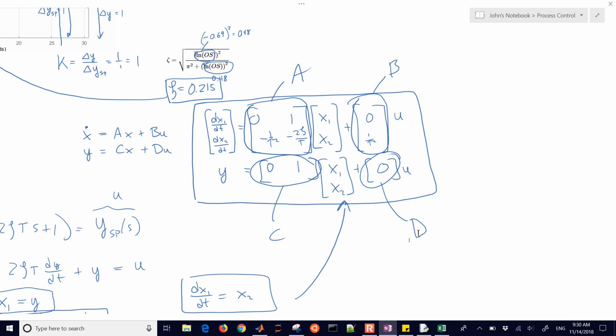There's a lot of things we can do with a state space form. For example, we can look at the eigenvalues of the A matrix, and it tells whether the system is going to be stable. We can also, this is in the time domain, so we don't even need to do anything in the Laplace domain. It's a very convenient form that allows things like model predictive controllers or other things you can do with linear time invariant systems. In this case, it's just a linear state space form.